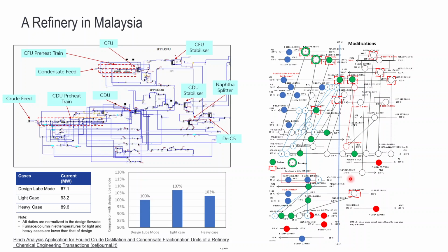It's heating up the stream from 175 to 178 degrees C with this 3 kilowatt per Kelvin, the MCP. And then this is the name of the heat exchanger, and this is the load of the exchanger, about 1 megawatt. Yeah, so that's how we draw this. And then typically we draw a heater, like red circles.